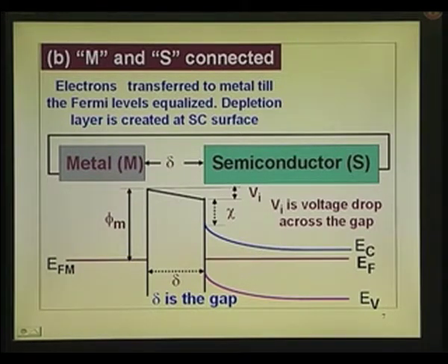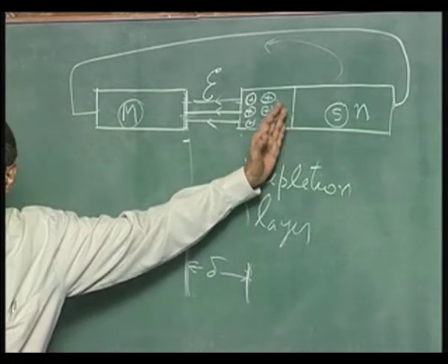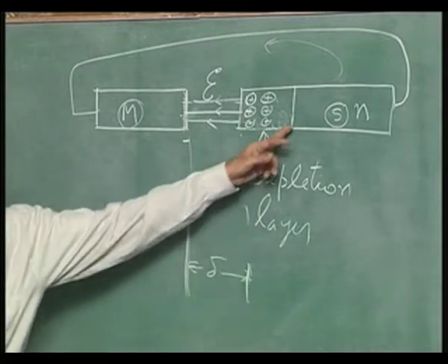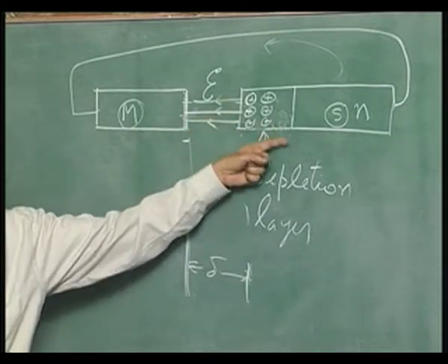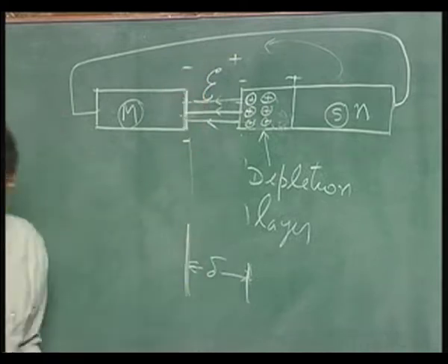So, you get the voltage change here, that is shown by the change in the conduction band variation, and beyond a certain point it is flat, and it is flat beyond this portion, because this is neutral region, there is no voltage drop. When there is no voltage drop, band diagrams are flat. Here there is a variation in the band diagram, because there is a potential change from here to here. This is positive, this is minus, this is positive, this is minus.